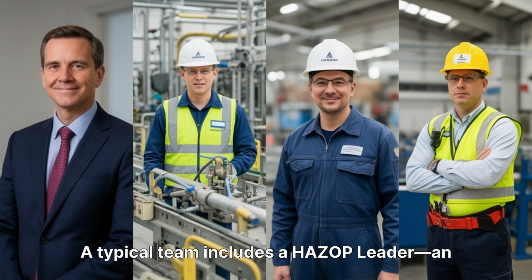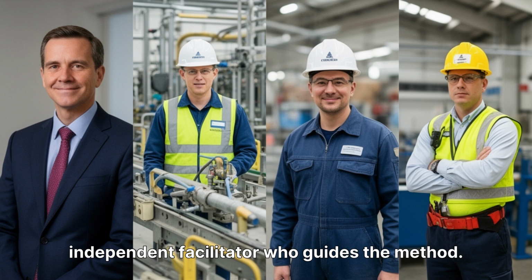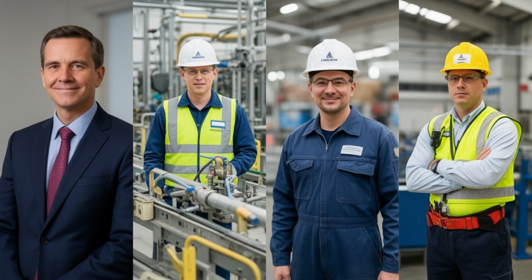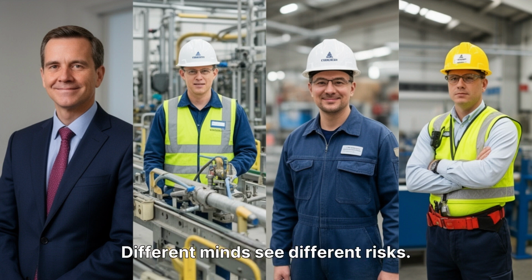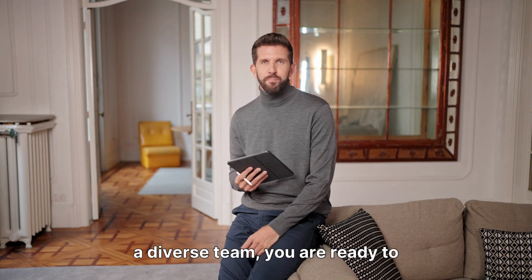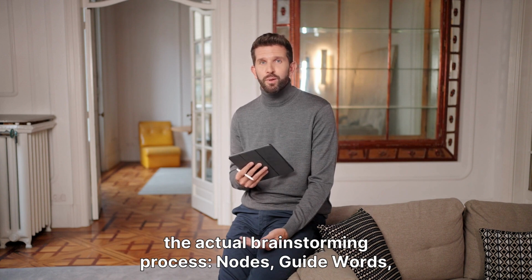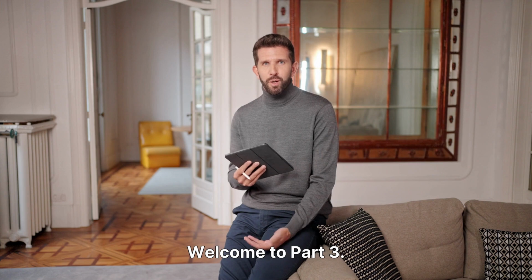A typical team includes a HAZOP leader, an independent facilitator who guides the method. You need a process engineer for the theory, an operations representative for practical insight, and experts for maintenance and instrumentation. Different minds see different risks. With the right timing, accurate data, and a diverse team, you are ready to start. In Part 3, we will break down the actual brainstorming process: nodes, guide words, and parameters. See you there.